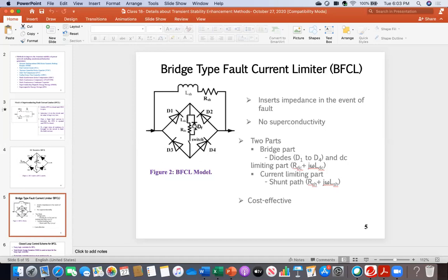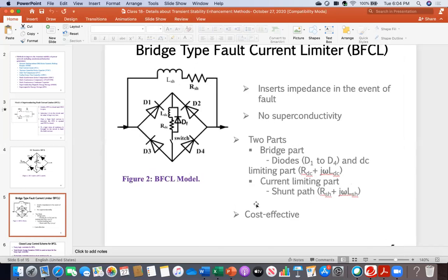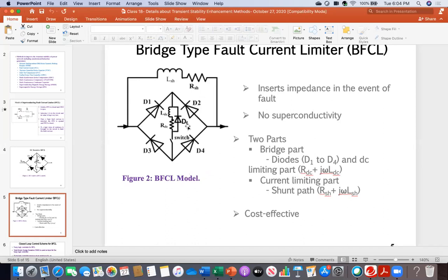That's why you see there is one diode. What will happen? Everybody, current was coming from top and it was going, switch got open. So current will start flowing through this way, through this diode. This is called the freewheeling diode, DF. Here you see there is subscript F. Yeah, can you see DF? It is called freewheeling diode.